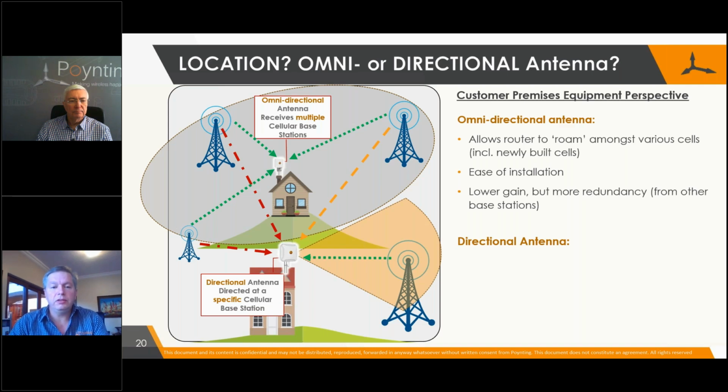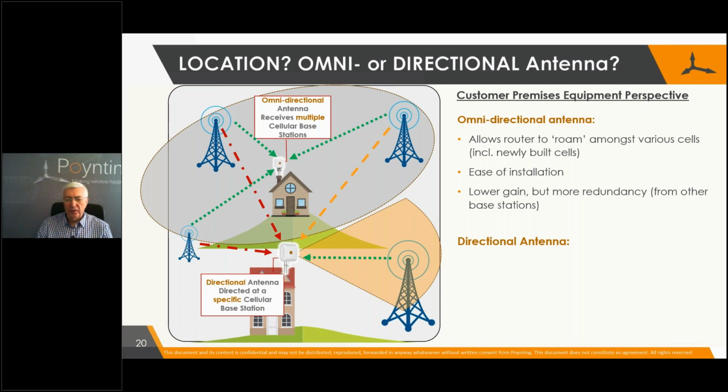If there's a way that you can shield yourself from those incoming signals, you actually get a better C/I, carrier to interference. So we often look at vast rural sites that have very low signal levels to rather use directional antennas where possible. So just a comment on that. Yes, thank you, Stephen, quite right. Thank you.